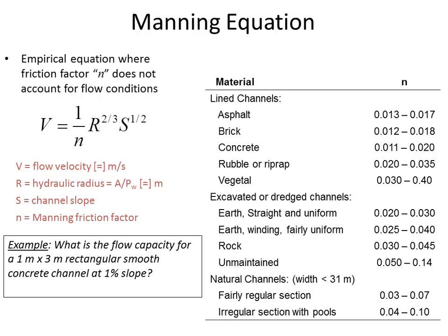There is something that's called the best hydraulic section. And we'll get into that in a future lecture, like these perfect shapes that have the optimal blend of minimizing the wetted perimeter. For a certain cross-sectional area, there is a shape that can minimize the wetted perimeter, whether it's a trapezoidal channel or triangular or circular, certain cross-sectional shapes that are optimal for design.